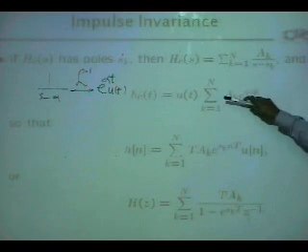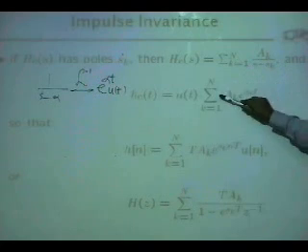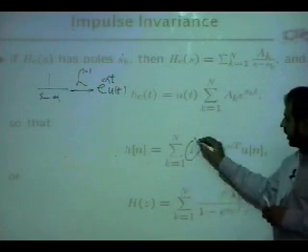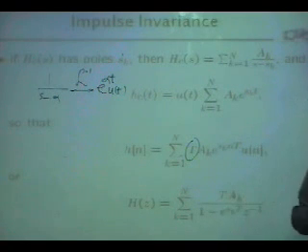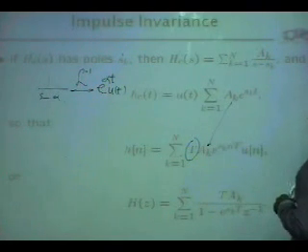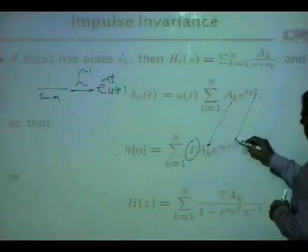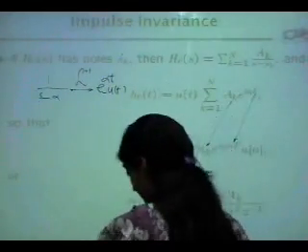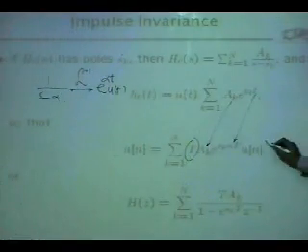Now we know the method. The procedure is, now you discretize it. You make h(n), but h(n) also comes with an extra T. This is for the scaling. So T a_k comes as is, and for t you replace it by n capital T, and u(t) means it is only for positive values of t, so you write h(n).